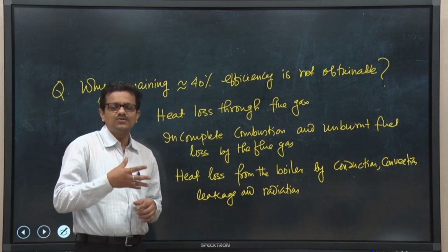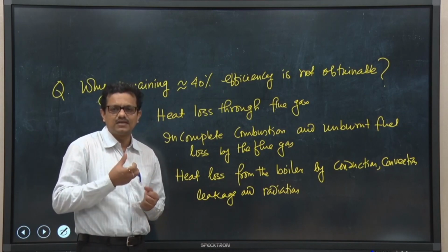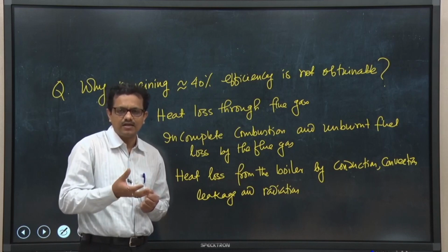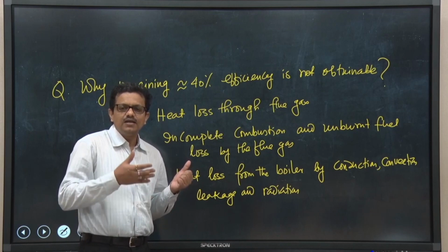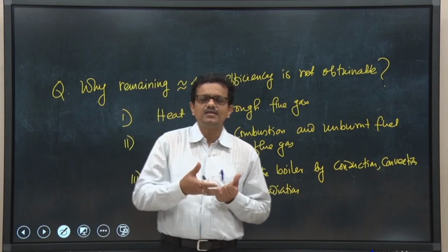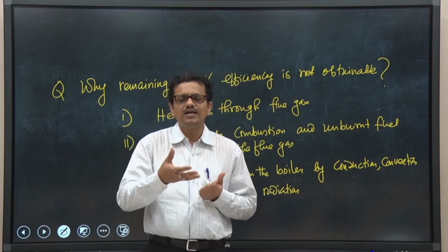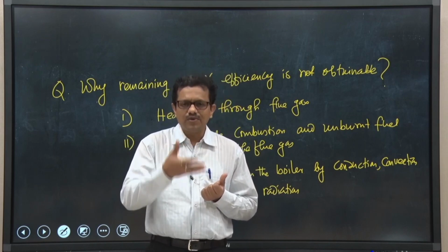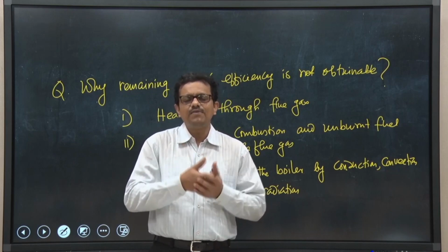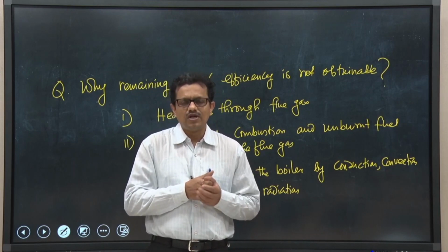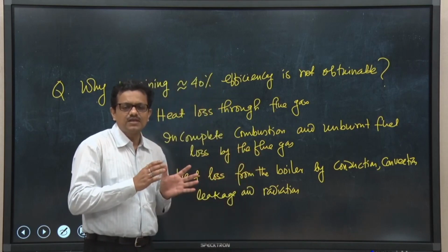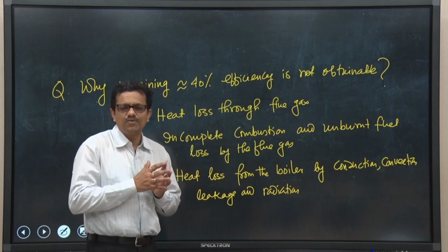Finally, we discussed that the sole objective of placing superheaters in the boiler is to get superheated steam, to increase the steam temperature before it enters the turbine. We have seen in practical scenarios that sometimes the temperature at the exit of the superheater is so high that we need temperature control. We have also discussed that part. And finally, we solved one numerical problem.